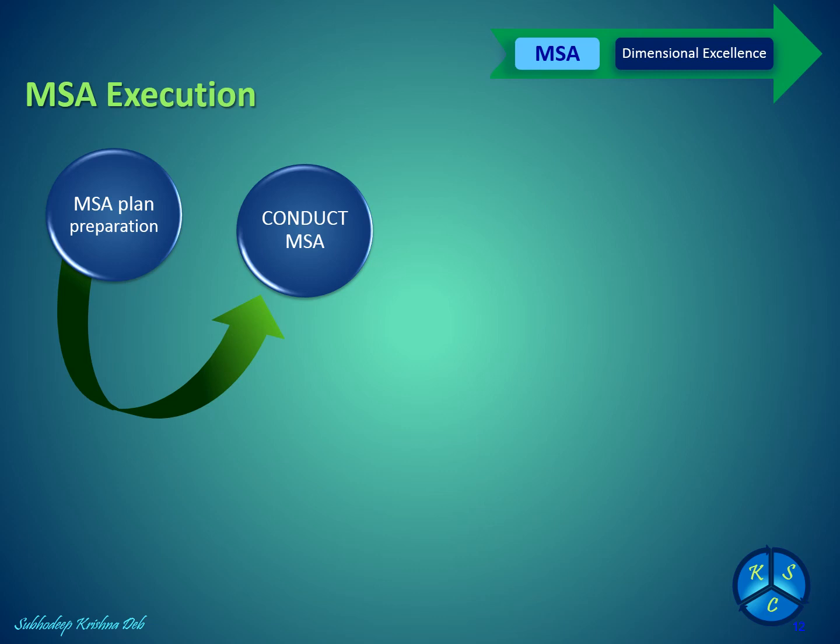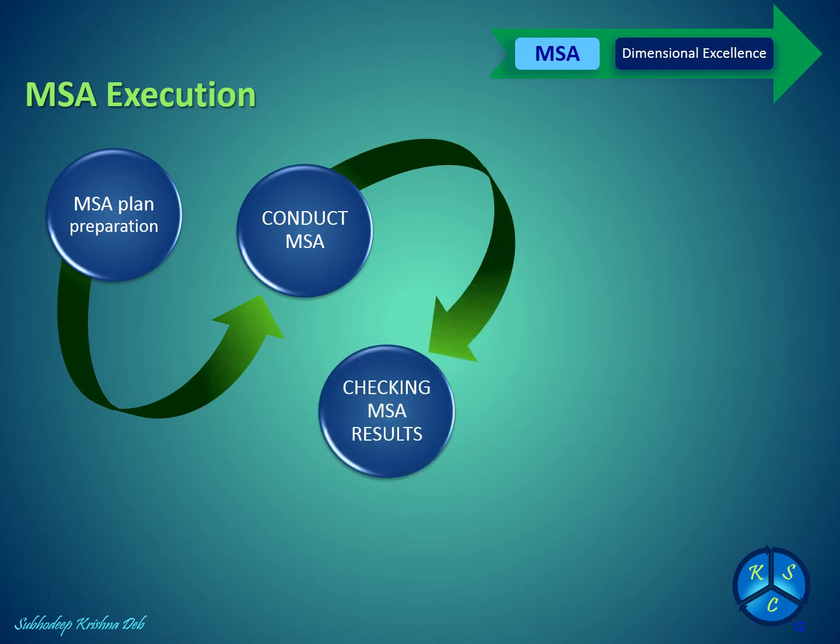We have to remember all the guidelines that we have discussed while conducting the MSA, and observers need to be established for doing the MSAs in different areas, segments or processes wherever required. After the MSA conduction is completed, we will get the final value, maybe the GRR value or the bias value or linearity or stability, and we have to check that result against the acceptance criteria.